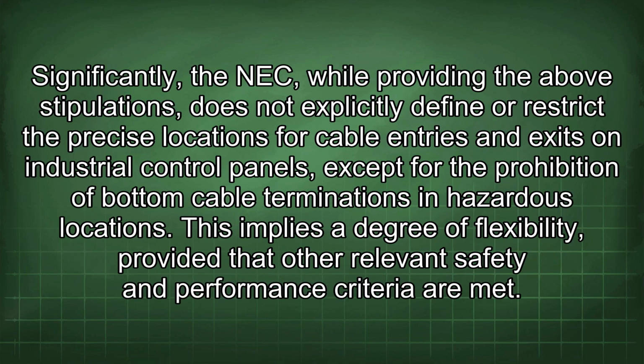Significantly, the NEC, while providing the above stipulations, does not explicitly define or restrict the precise locations for cable entries and exits on industrial control panels, except for the prohibition of bottom cable terminations in hazardous locations. This implies a degree of flexibility, provided that other relevant safety and performance criteria are met.